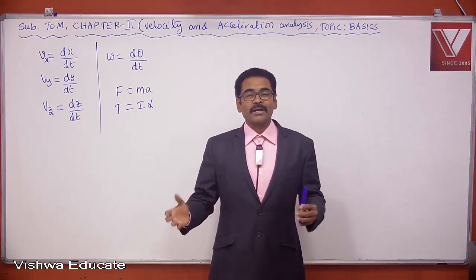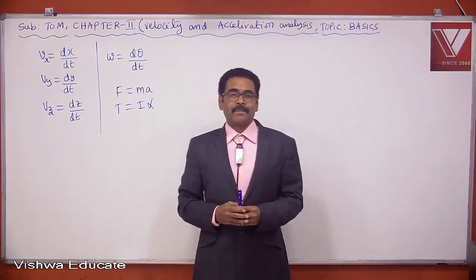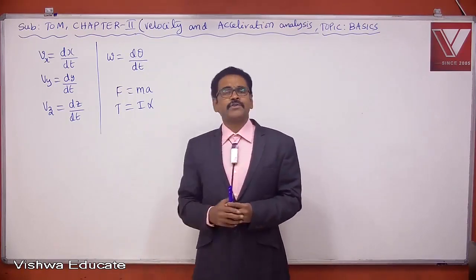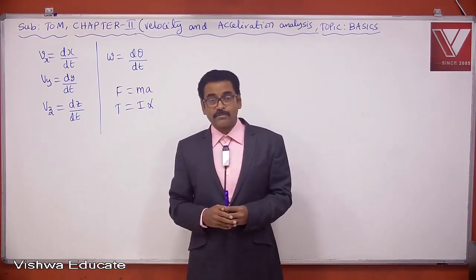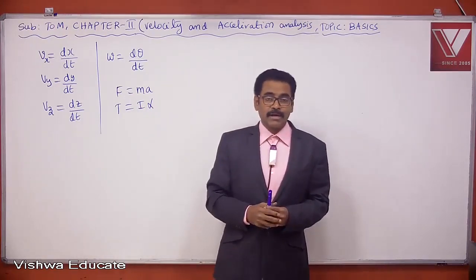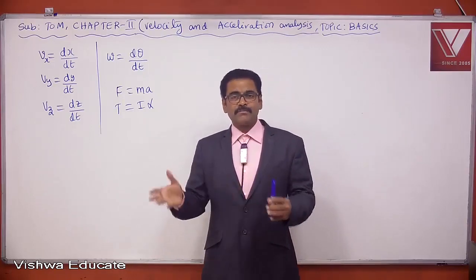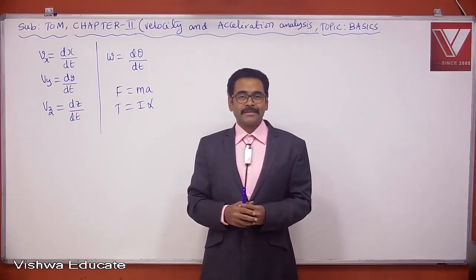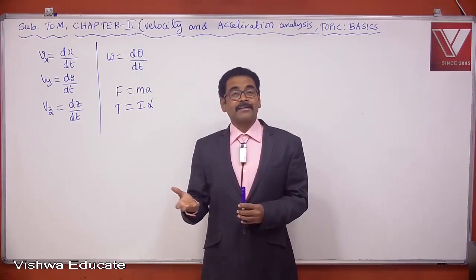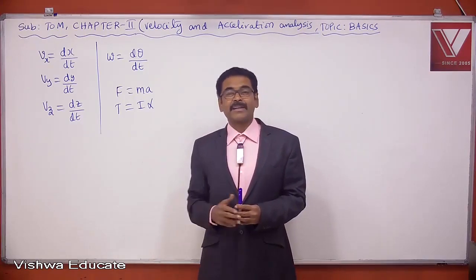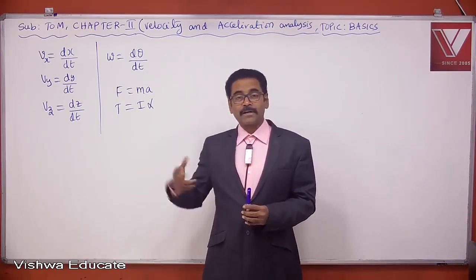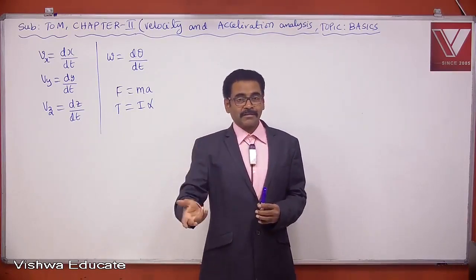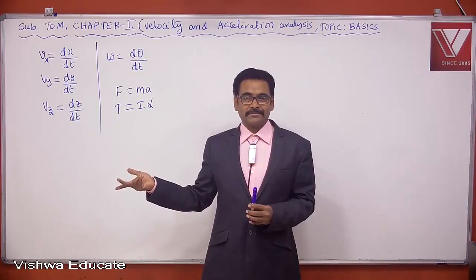We have to conduct balancing. We have to balance the engine, the machine, the unbalanced force and the unbalanced couple. This is called balancing. Balancing is the process of eliminating unbalanced force and unbalanced couple either by adding mass or subtracting mass.